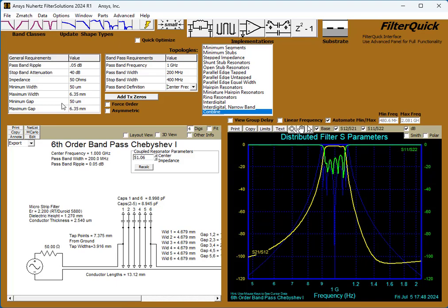Remember that the dielectric thickness in any design is selected so that the impedance of the RF lines doesn't change more than 10% with the worst manufacturing tolerance. You can also set a maximum for the width and maximum for the gap. Just select a big number, but don't allow it to be infinity. Like, put some numbers there. Based on the numbers you give, the software will choose the order of the filter, but you can impose the order. You can force an order if you want here.